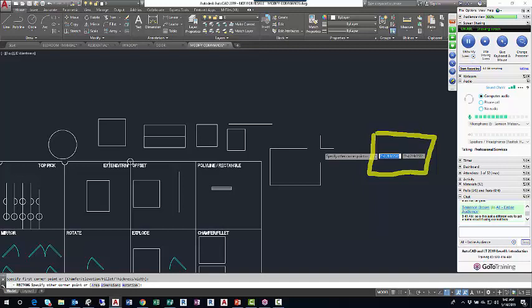So if I want this desk, I'm going to draw a desk, air quotes. If I want this to be 60 wide, my X is going to be 60. So I'll type 60, and then I'll press the Tab key. This is like filling out a form online. I press Tab, it closes the X window, opens the Y window. Now I'll type in 30, and I'll press Enter. And that created this very specific sized rectangle.